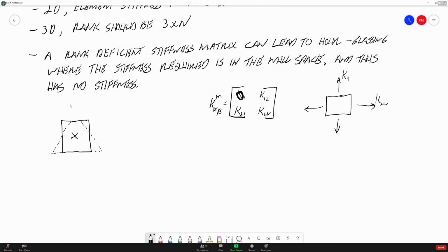And what it comes down to is, if you have a single integration point here, and we find our stiffness characteristics of this, there's not sufficient stiffness, a mathematical stiffness representation for this square to keep this from happening.